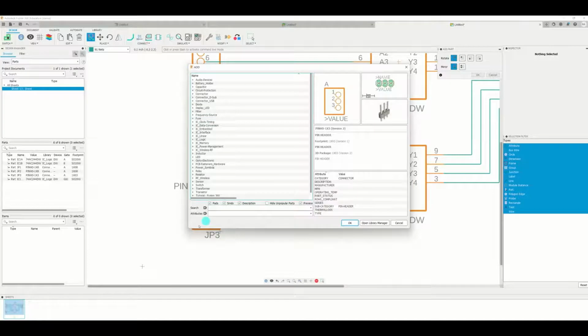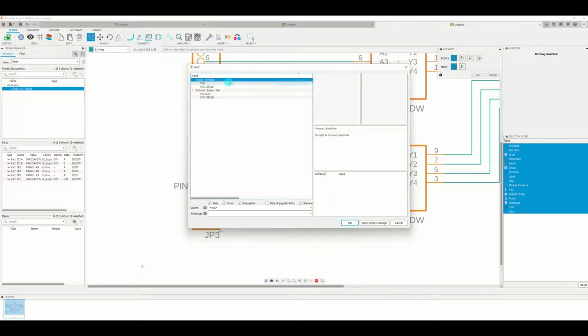So one way of doing it is we can, by the way, type symbol here. So if I type asterisk here, then VCC and asterisk. So what's happening is I'm looking for a component or a symbol with a VCC. So if I do OK, you'll have these power symbols here for the VCC, and you can select this one or the circular one.